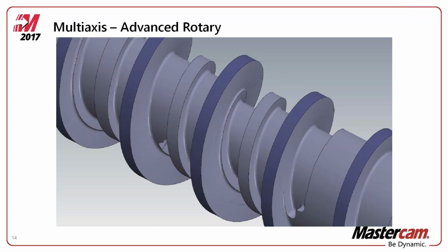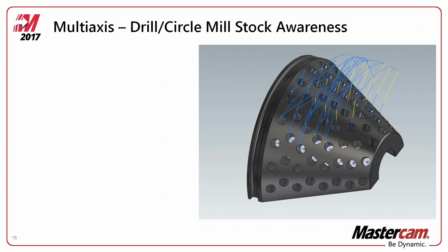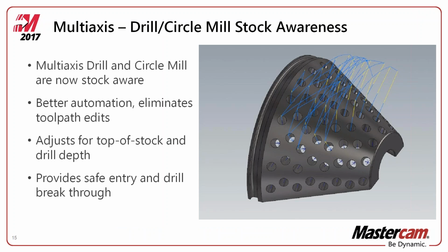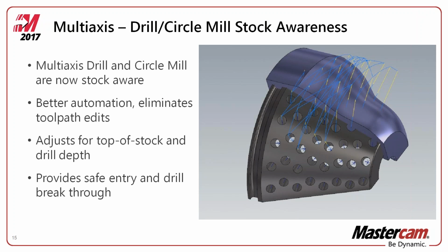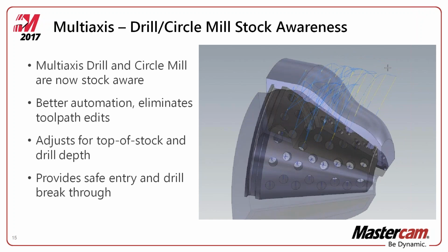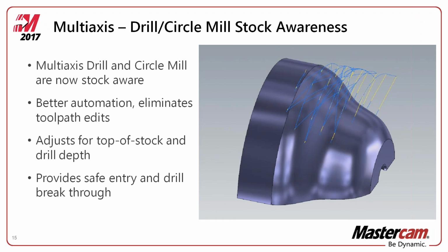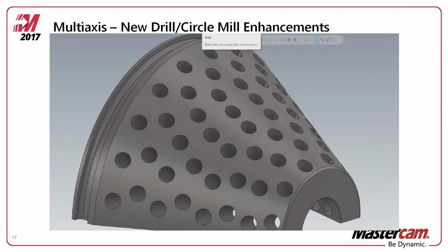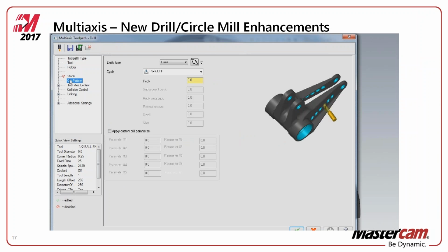Some other nice things as far as the toolpath goes are with the drilling and circle milling. So some more automated ways to use that. It is now going to be stock aware, where it's basing its toolpath off of that type of stock. Also with that, a couple enhancements as far as how we can select those holes.